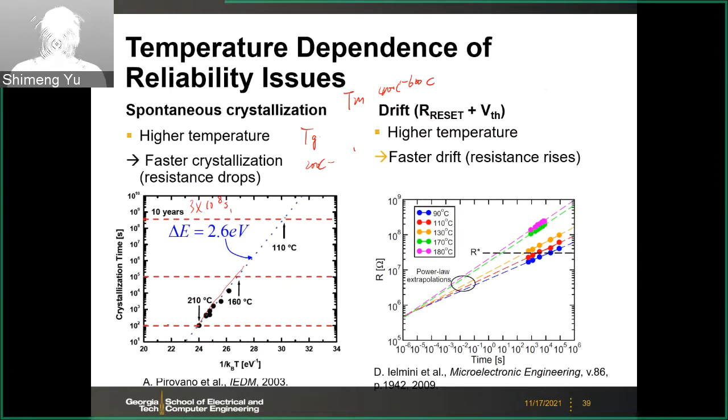And if you do that, you back calculate what is the temperature for this one. You first look at the kT in electron volts, and then you convert back. That is about 110 C. So that means this device can sustain the temperature 110 C for 10 years.